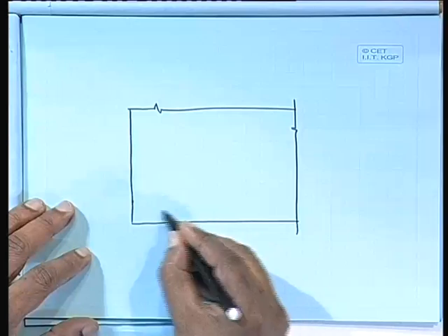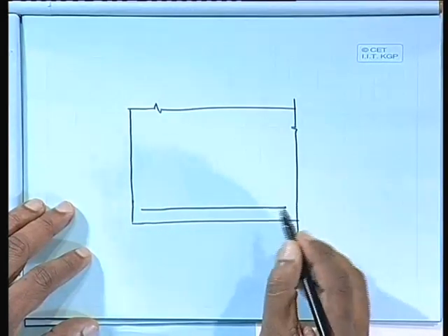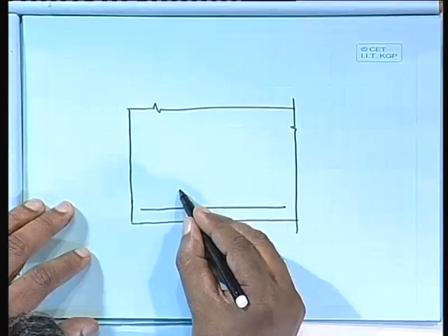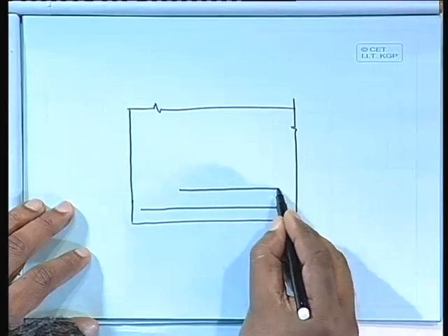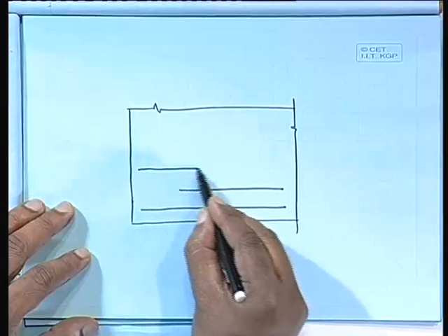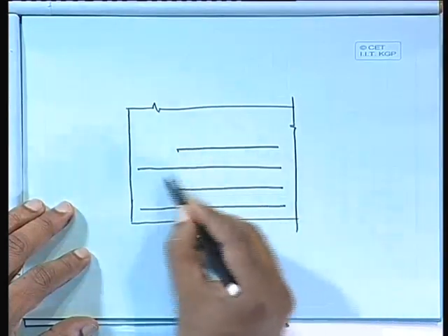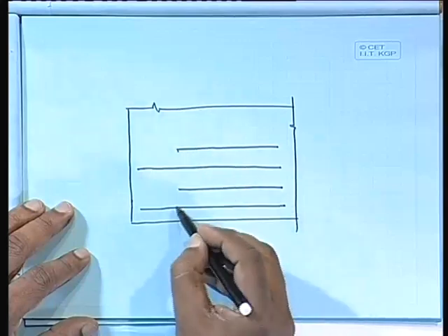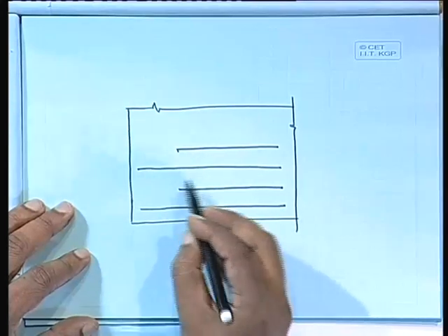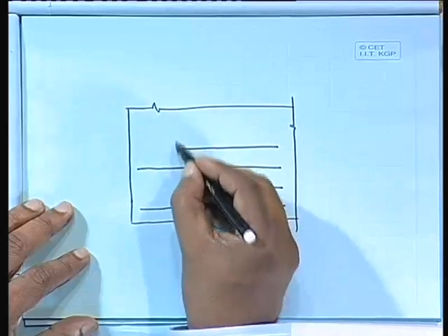So, say this is one bar in the bottom, the other bar we just simply cut it here. That is, I am talking about the bottom. Similarly, another bar here, the other bar which is coming here, because we do not require that much spacing at the bottom. So, here we can just curtail the bar. So, that is the idea.